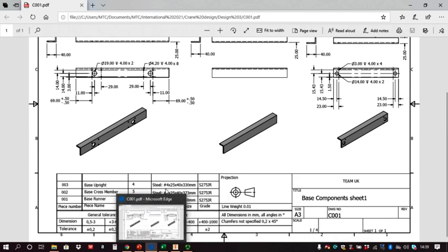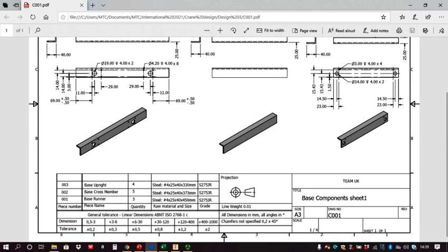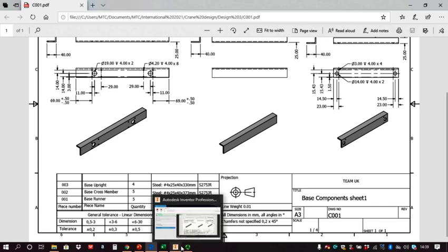Okay, so I can't actually cut on the other two lines because it's stock material, so it only has to be 50 millimeters too long in one direction. It would be a bit different if it was a sheet. It would have to be in two directions. Okay, so stock material, one direction, 50 millimeters over, but I have specified raw material and size.